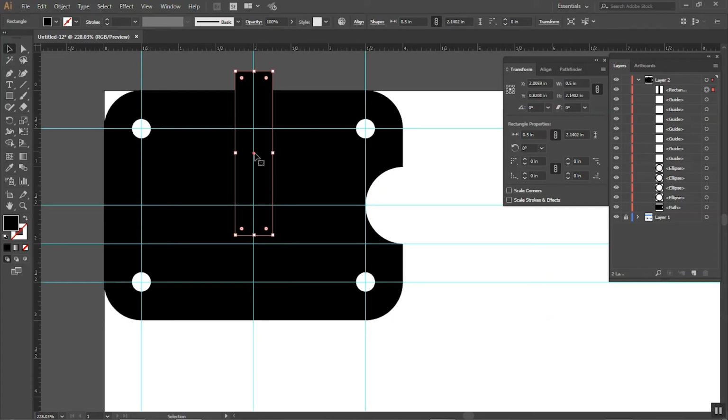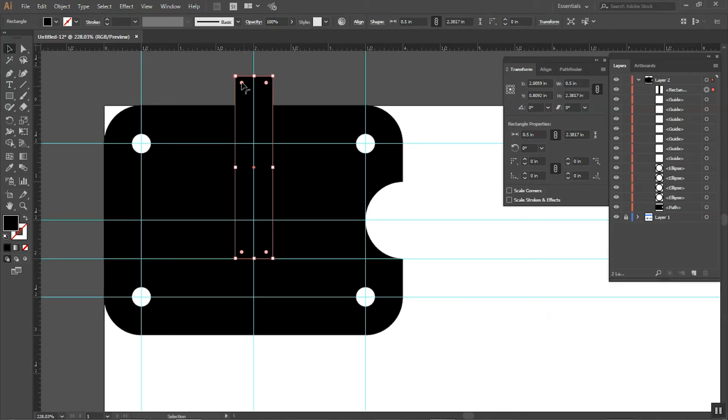And then if I move the whole thing, holding down Shift, you'll notice it intersects there and snaps. So we can overlap at the top, and then we'll just add these, I'll drag this up a little. These points here, when I hover over them, you notice it shows a little fillet icon. So this is actually, because all 4 are selected, as I drag them in, you'll notice it go to 0.25.